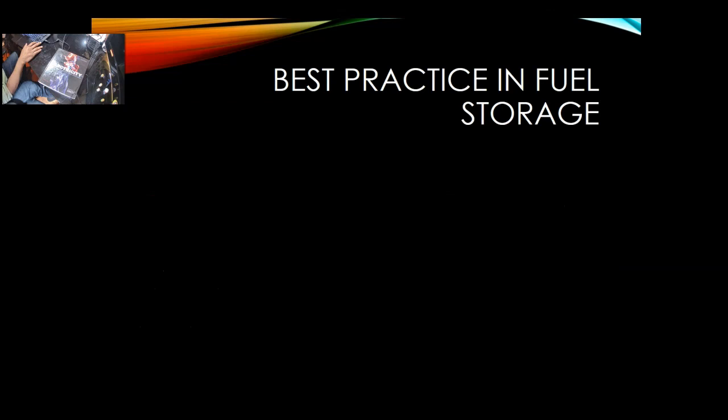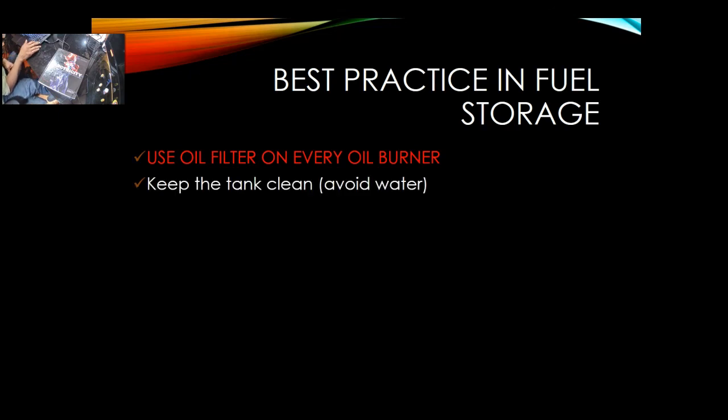Best practice in fuel storage. Use an oil filter on every oil burner. Change that oil filter every season. Keep the tank clean. Avoid having water. You're going to have water from the room. How is that? Whenever you take out oil, you're going to bring in air.